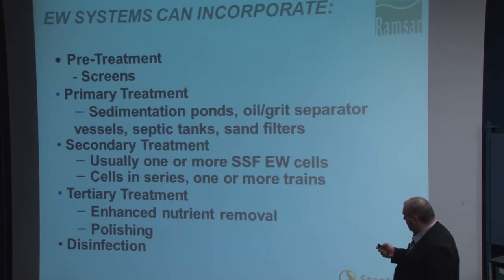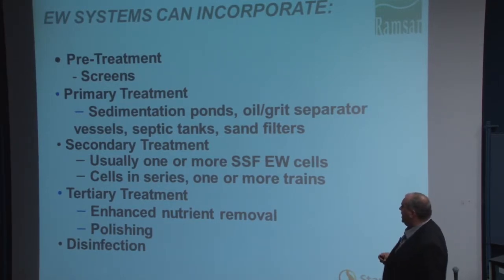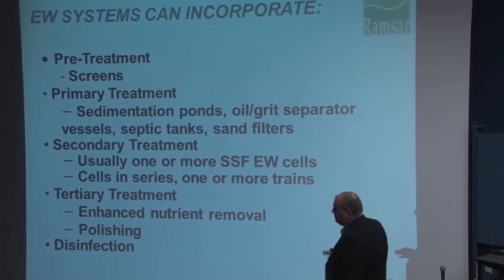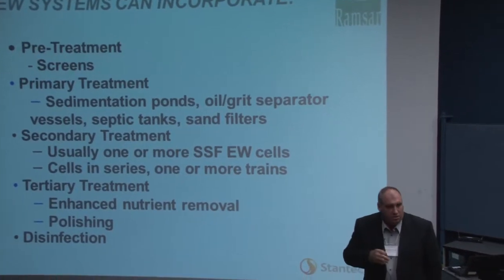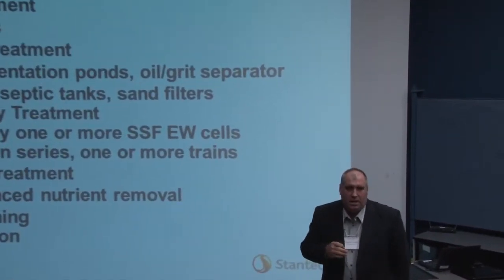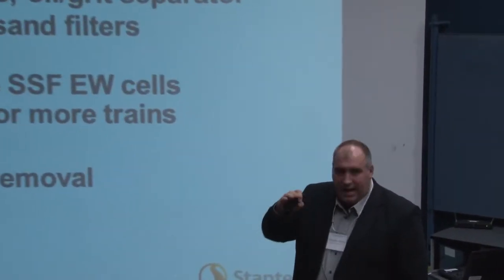Secondary treatment is really where the engineered wetland comes in. And they're often done in a single, but more commonly, multi-cell system, where the cells take the stream through a variety of processes. We may be going from anaerobic to aerobic processes, or vice versa.